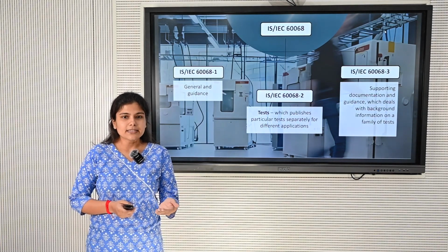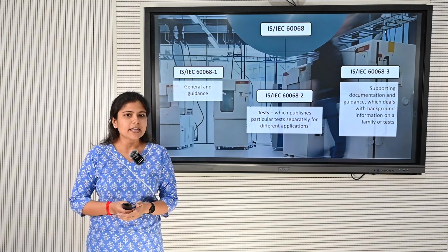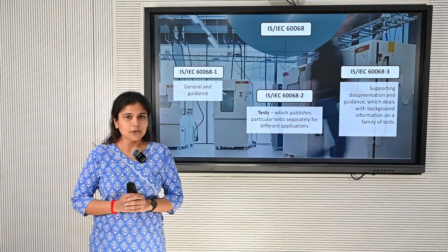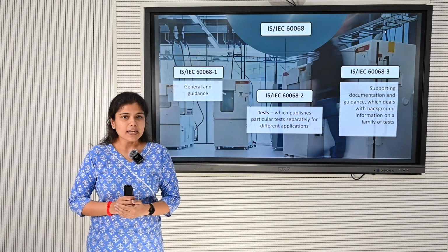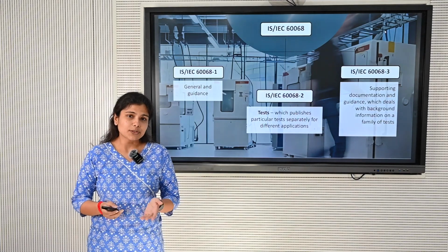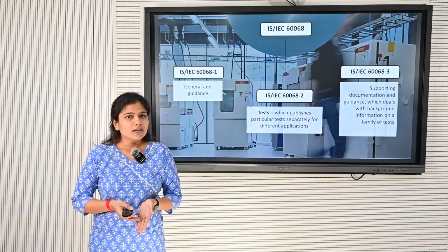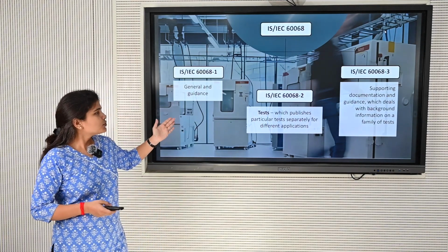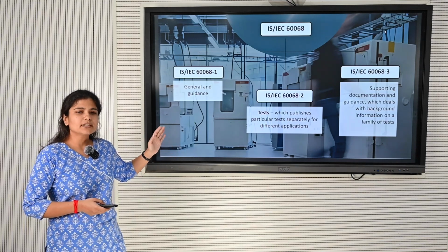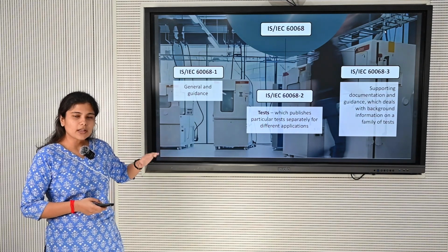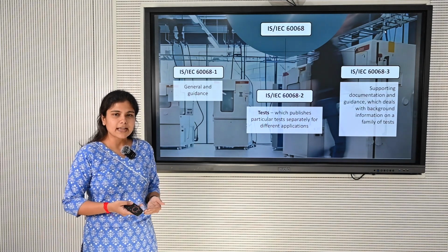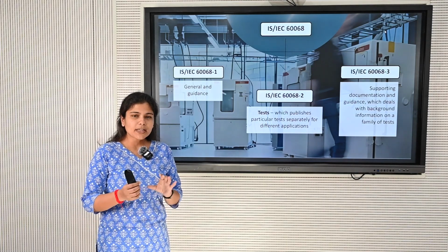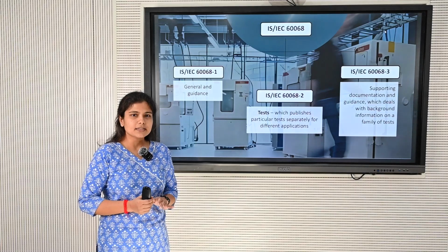For example, there is temperature condition, there is humidity condition, there may be aspects of mold growth on the particular product, there are pressure conditions as well, and there are mechanical conditions as well. So part 1 talks about the general guidance of all these products, how to perform the test, what should be the preconditioning when you are putting a particular device under test.